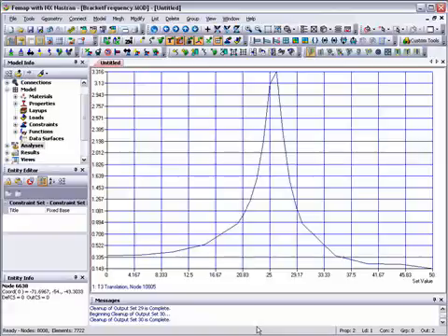Therefore, with the requirement to maintain a deflection of less than 1 mm at the motor center of gravity node, any dynamic base excitation loading with a frequency between 20 Hz and 30 Hz would require a redesign of the bracket. This shows that in many cases, a simple static analysis review is not enough. Femap with NX Nastran can take the analysis further and model a more realistic representation of the design and its working environment to give more accurate and complete answers.